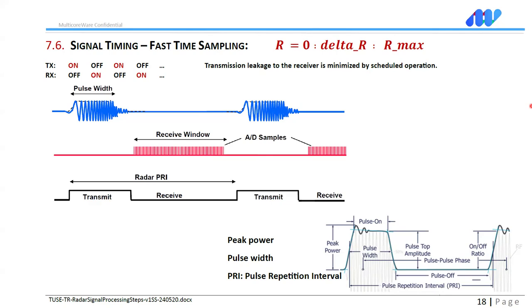And think about it. If the transmitter and the receiver utilize the same antenna, or the TX signal is highly coupled to the receiver, for example in the monostatic case, where both circuits are very close to each other, then this huge signal definitely saturates the receiver, and the receiver is blinded by the strong TX signal.